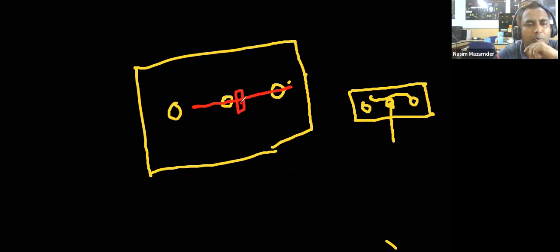If this plunger is coming to this side, then air will be passing through this port. If this plunger is going to this side, then air will be coming to this side. So these are internally connected, a solid design, and they depend on the position of the spool. This is called your spool or plunger or some kind of ball, and this is pulled or pushed through your solenoid coil, the supply of the solenoid.